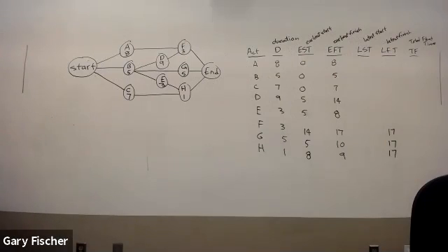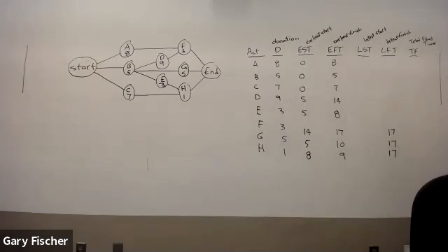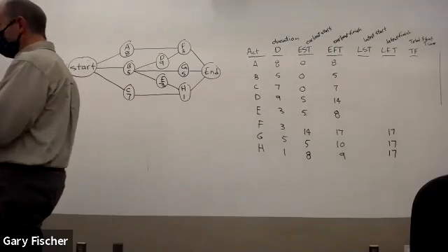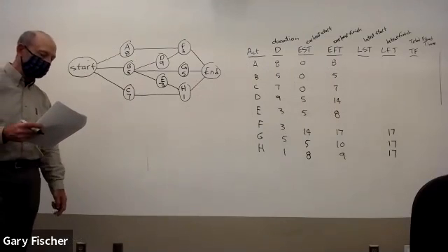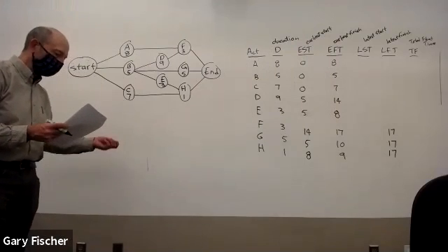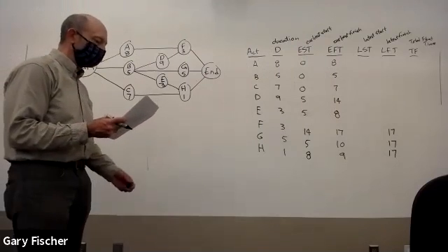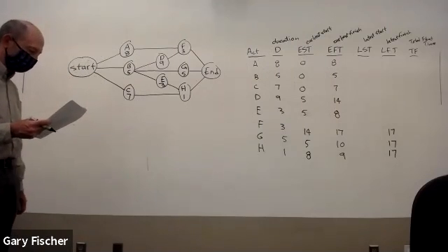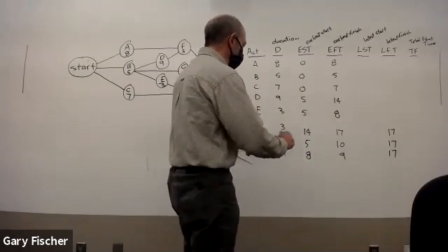Okay. Let's see here now. Why is that though? So now I have to read here. Activity D is proceeding. Okay. Accordingly, okay. All the activities preceding the project finish are all day 17, since no activities follow them. Okay, so we listed those. The latest finish times of activities G and H are day 17. That means then we can calculate the latest start time of those activities by subtracting the duration from the latest finish time. So for F, let's take an example.